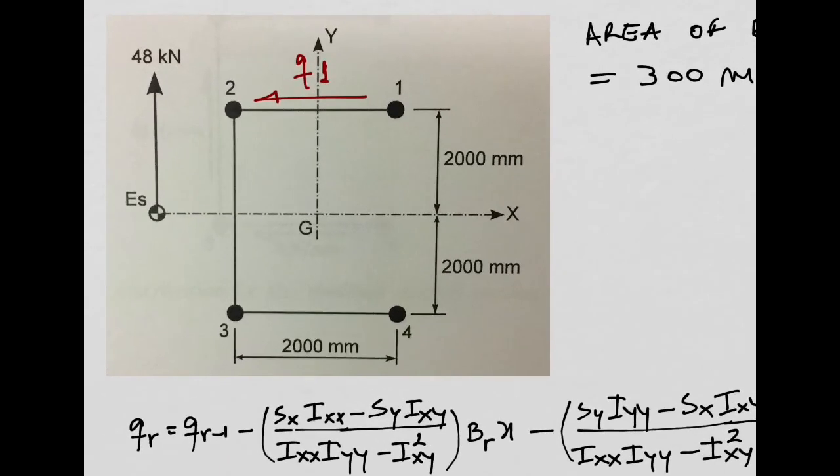And then after crossing boom number 2, I will have a shear that will flow in this direction. And this shear I'm going to say is Q2. It is going to be constant in this skin between boom 2 and boom 3, but this Q2 is going to be different from Q1 because I crossed the boom. Okay? And then when I continue, the shear will continue to flow, and then it will go on this skin here, and then this shear is going to be my Q3. All right? So that's the first thing we have to do.